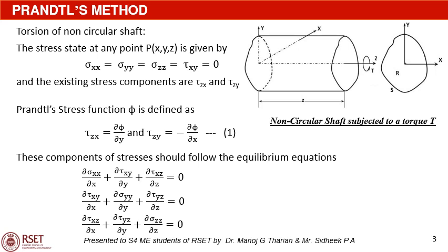The stress components should follow the equilibrium equations, which are given by ∂sigma xx/∂x plus ∂tau xy/∂y plus ∂tau xz/∂z equal to 0, ∂tau xy/∂x plus ∂sigma yy/∂y plus ∂tau yz/∂z equal to 0, and ∂tau xz/∂x plus ∂tau yz/∂y plus ∂sigma zz/∂z equal to 0.